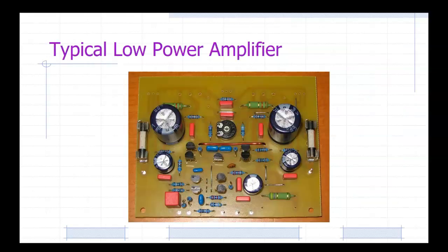Because that's what it looks like in actual life. Okay? I don't get to see all the wiring, do I? Not on something like that. Now why? Why don't I want to see all the wiring? Because, I'll put it this way, traces are very delicate. You don't really want them exposed to anything because if you have them exposed, what is the easiest thing to happen? Something comes along, scratches it, and that printed circuit board is toast. Because you cannot repair traces. It's impossible.